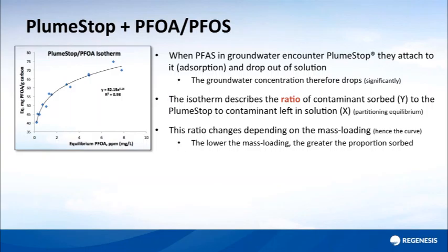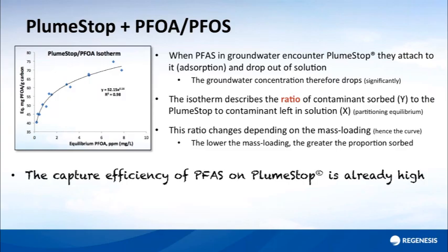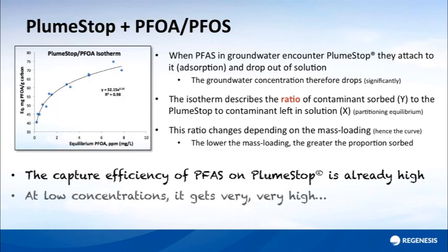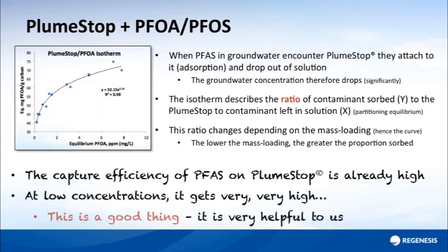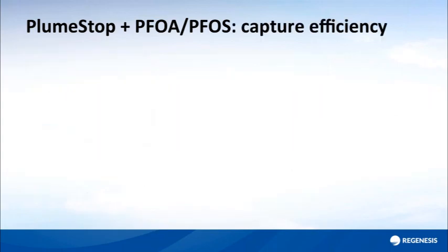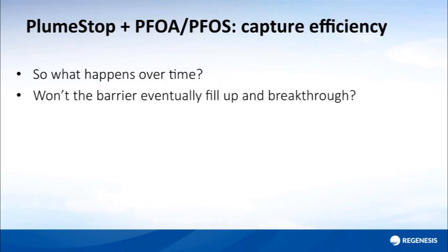To give an indication of that, well, another question first. What happens over time? Won't a capture barrier eventually fill up and break through, given the perfluorinateds will not biodegrade? Well, the answer is yes, it will eventually fill up and break through. What's important is how long it will take for that to happen. How long this is going to take is described by the retardation factor, and this will be governed by the contaminant's concentration, contaminant mix, and the PlumeStop dose.